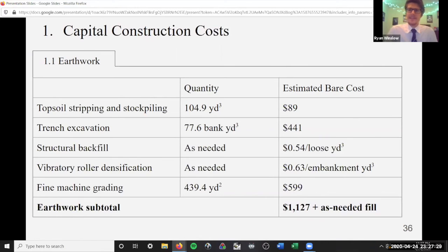The site the dark tank and UV modules will be built on will be assumed to be of a sandy subgrade with light grass cover. Before the foundation with strip footings can be installed, some earthwork must be performed. This includes topsoil stripping and stockpiling and trench excavation.